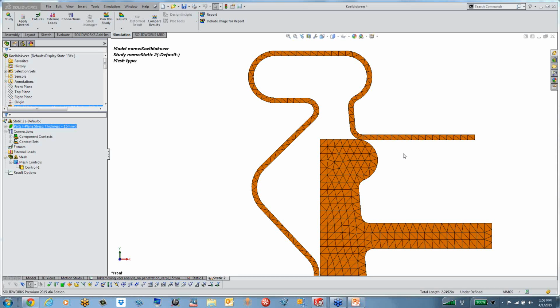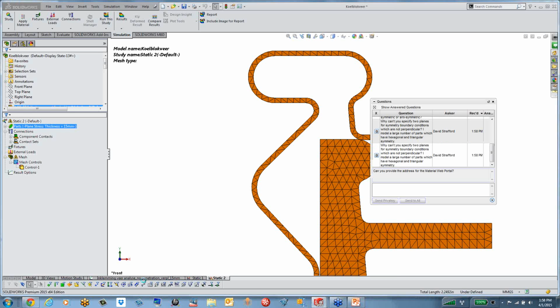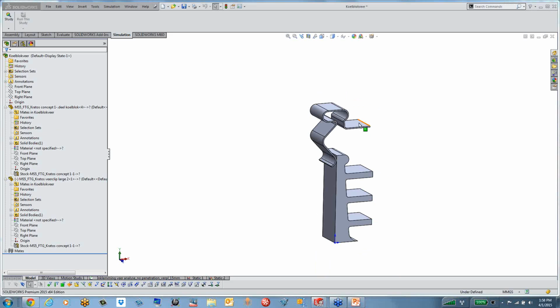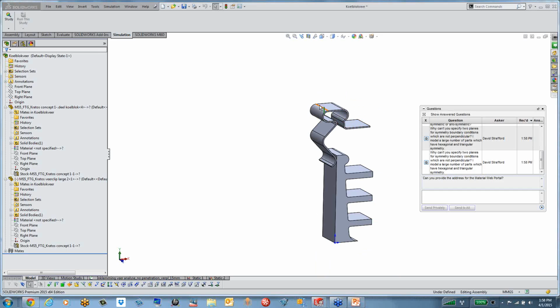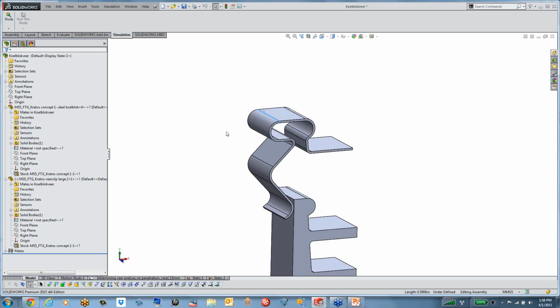Okay, if you have any kind of a structure that's a revolve, has a single axis of revolution, then you might actually want to take advantage of 2D analysis there as well. Okay, so there are certain rules that actually will help you translate a 3D problem into a 2D problem. So here, for example, it's a 2D problem because the full 3D model, you can see that the thickness is much smaller than the width and the height, and so I'm thinking that the analysis can be simplified to a 2D scenario. But that's the number one rule, looking at the geometry.